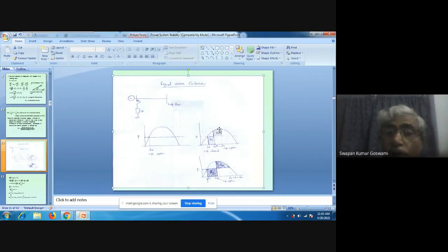So this A2 here, you see, is again representing some energy. Is it clear? But what energy? This energy A1, you see, was actually injected into the machine, because power was supplied, power was given as input to the machine, but the machine could not deliver any power output. So it was as if some power injection by the generator turbine to the rotor of the generator. It was some power injection, and because of this, the generator could store energy. So, power injection from outside.